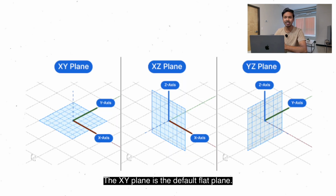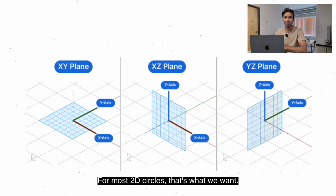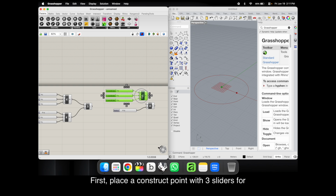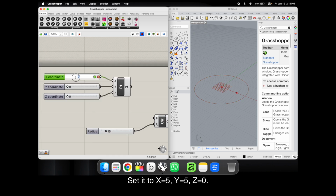The XY plane is the default flat plane. It lies flat on the XY floor facing upward. For most 2D circles, that's what we want. So here's the process to put a circle at a specific point. First, place a construct point with 3 sliders for the center position. Set it to X5, Y5, Z0.